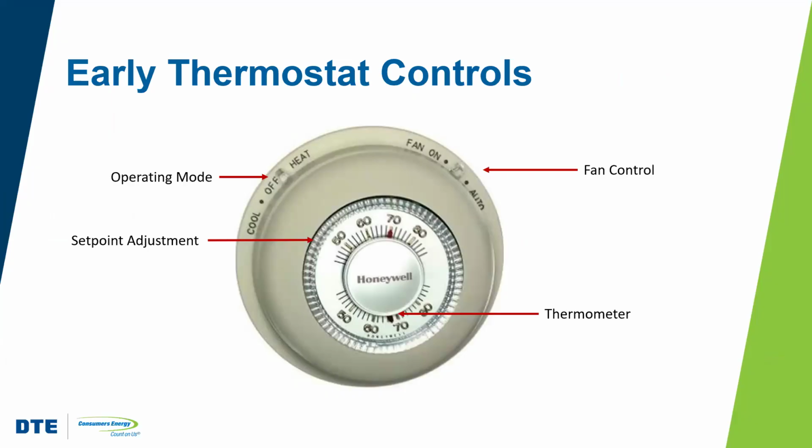This iconic round thermostat has some of the early controls. Obviously, it has an on-off switch. This particular model can switch between cooling and heating, which was a later development. You can see there's a set point adjustment here where we tell the thermostat what temperature we want to keep the space at. Here's a thermometer that tells us what temperature the space is actually at. And then here's a fan control, which either turns the fan off or lets it run in auto. In auto mode, the fan runs only when the system is heating or cooling, and on runs the fan continuously.